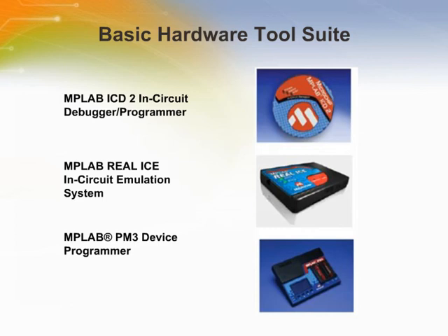MPLAB IDE is designed to work with all of Microchip's in-circuit emulators and programmers. The Microchip 16-bit families are supported by the MPLAB ICD2, MPLAB REAL ICE, and the MPLAB PM3 programmer. All of the tools are designed to work with MPLAB. MPLAB ICD2 is a flash upgradable in-circuit debugger designed to operate with any PIC microcontroller. The MPLAB ICD2 can be connected to and powered by the USB connection on its host PC. It can also connect through an RS-232 port.